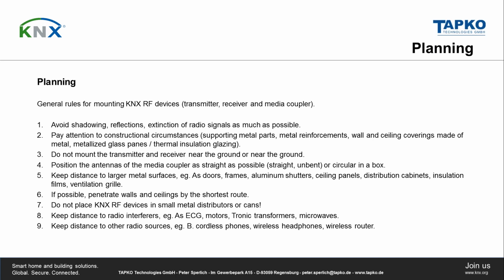The antenna must be really free. When you install them, don't fold the antenna if there's an antenna on the device, and also keep distance to things that could interfere, like engines or transformers or microwaves.